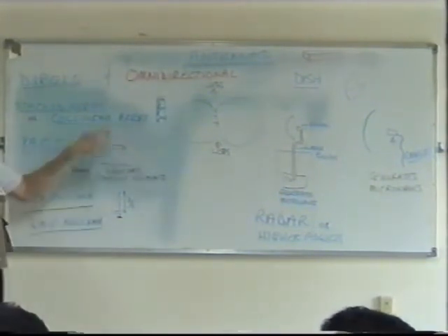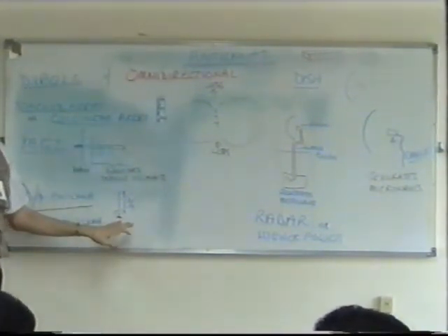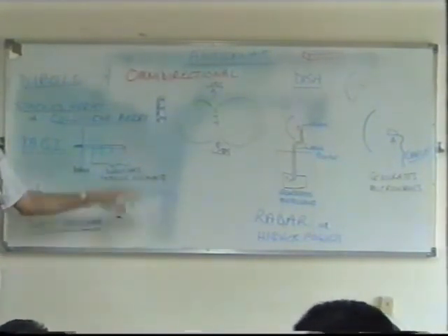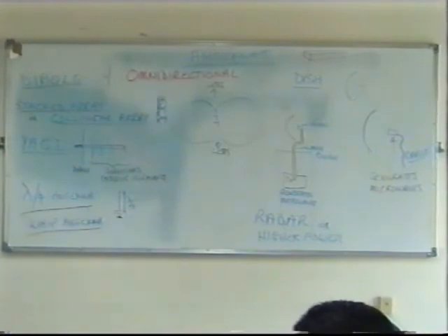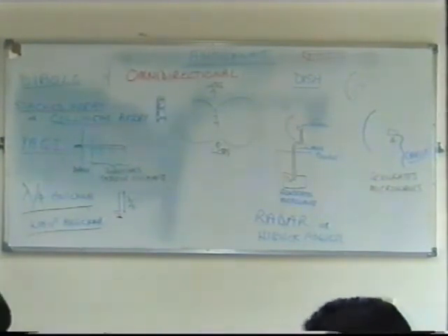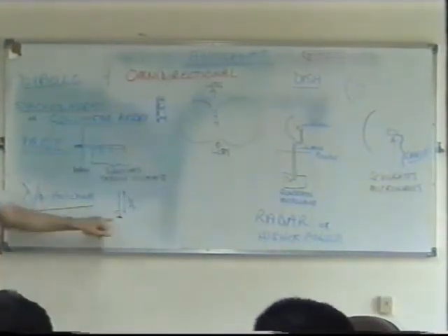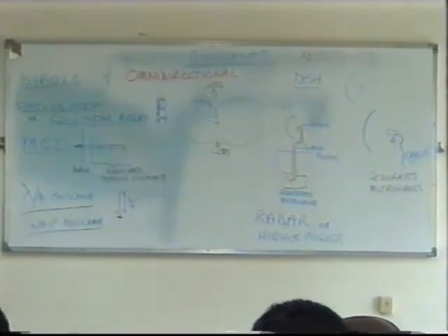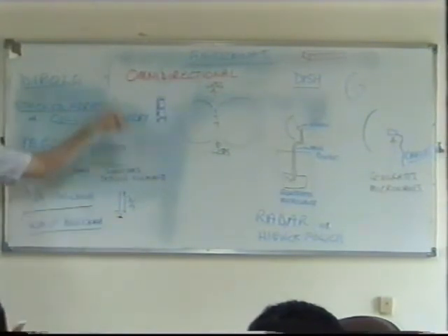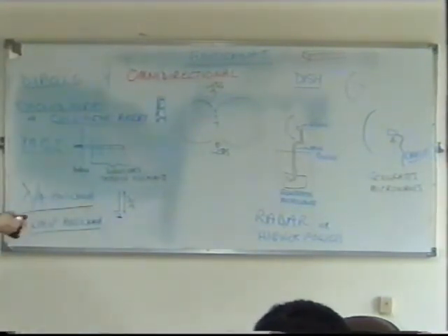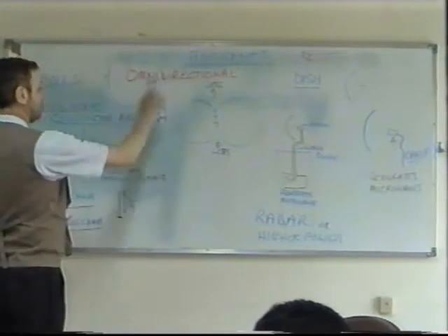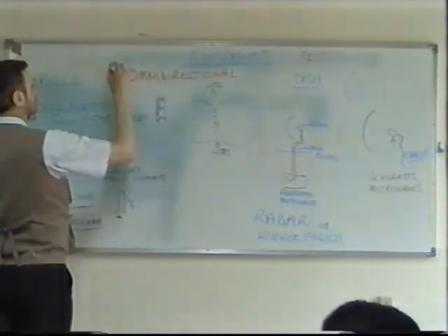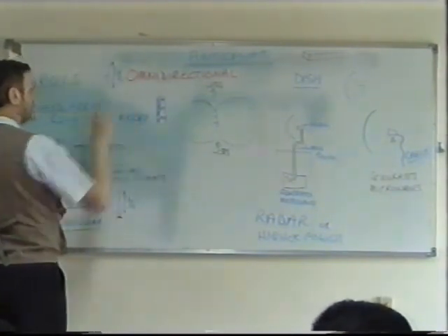Same thing. Or maybe even a whip antenna, because this is very similar to the dipole. Not quite as efficient, because it depends on how good the ground is here. The whip antenna is the same, but it's still omnidirectional. Yes. Sometimes it's called a whip antenna. This is a quarter wave. Dipole is half a wave, isn't it? Yes. But it's the same, omnidirectional. This is just like a resume of what we did yesterday.